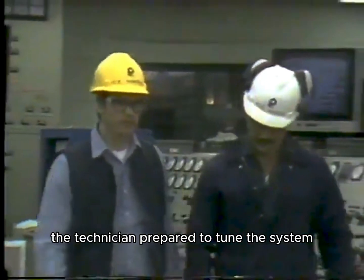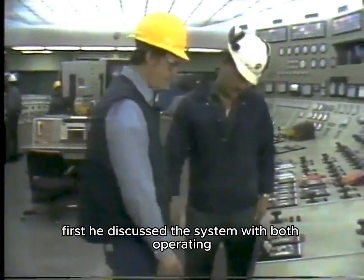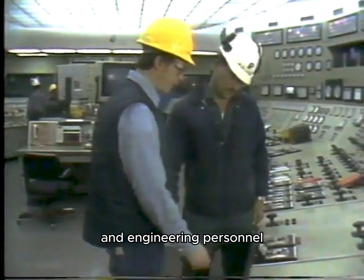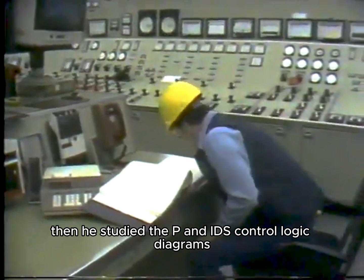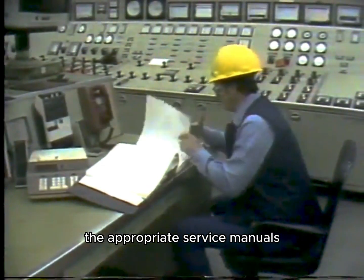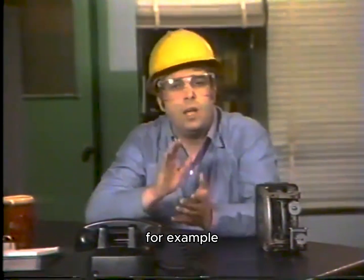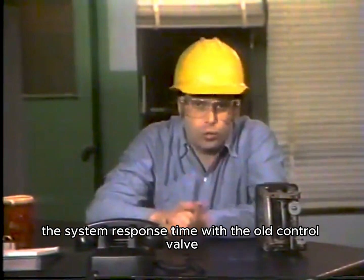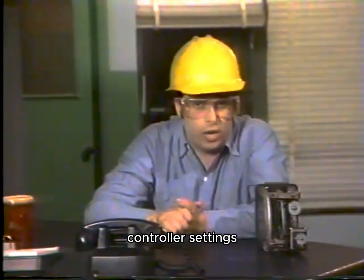Let's see how the technician prepared to tune the system. First, he discussed the system with both operating and engineering personnel. Then he studied the P&IDs, control logic diagrams, the appropriate service manuals, and the calibration records. After studying the system and talking to the right people, he had learned what he needed to know to tune it. For example, the system response time with the old control valve was 15 minutes. The engineer assured him that the new controller settings should keep the response time at about 15 minutes.